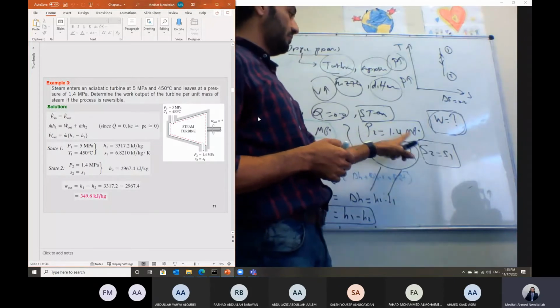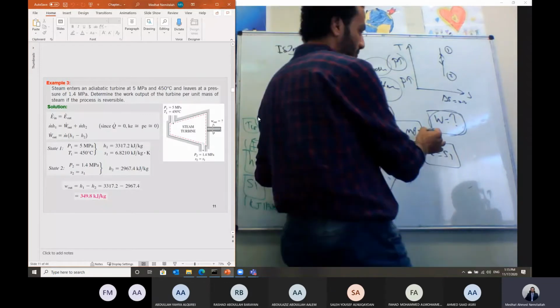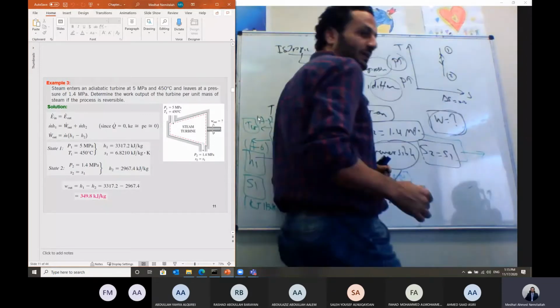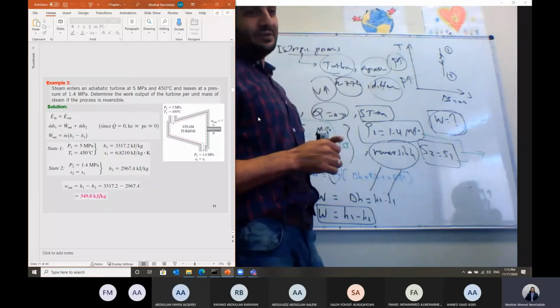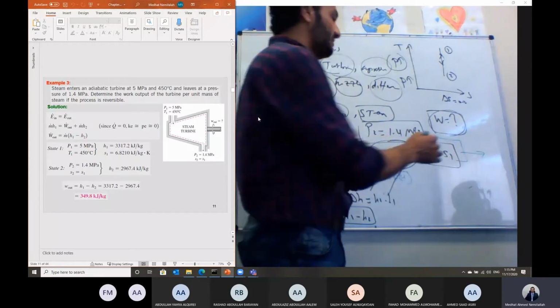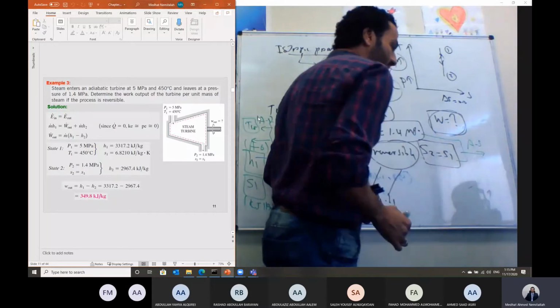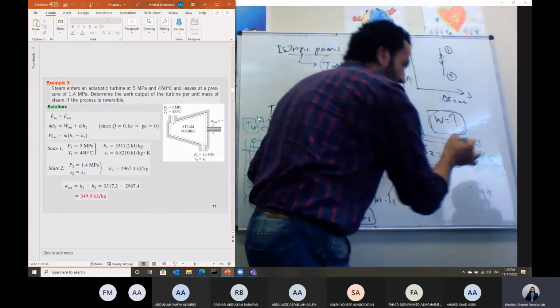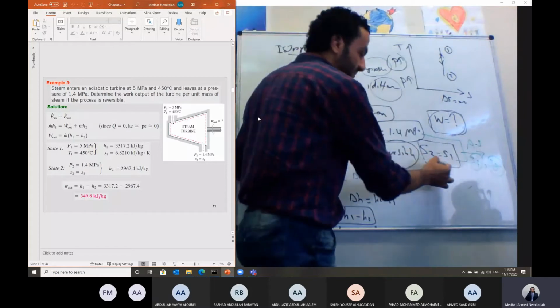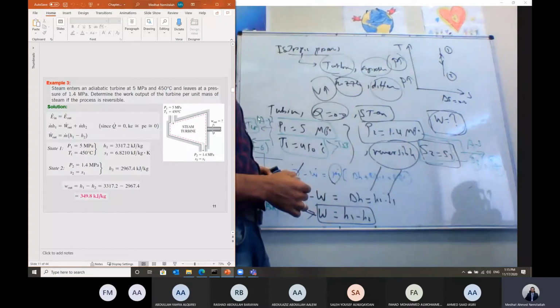I have pressure with one specific property. So what should we do? I'm just trying to revise with you what you have done in chapter 3. Okay. So with this pressure, I will be going again to table A5. I will get S fluid, and I will get the value of S gas, and compare it with the given entropy, which I got at point 1.